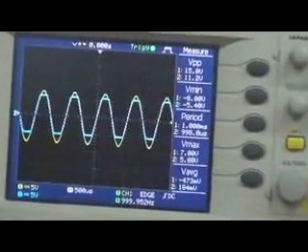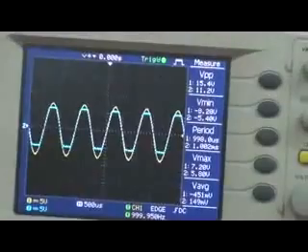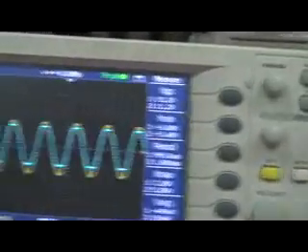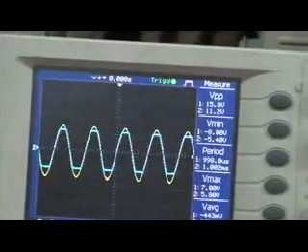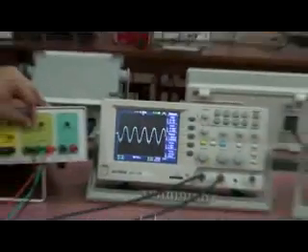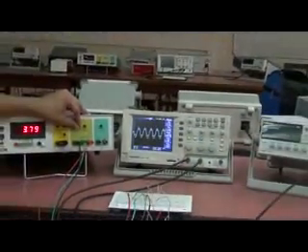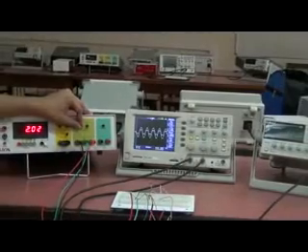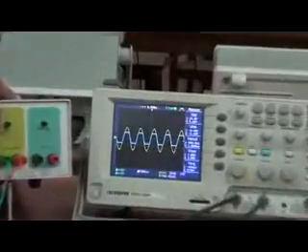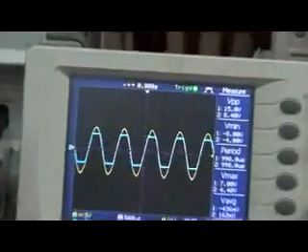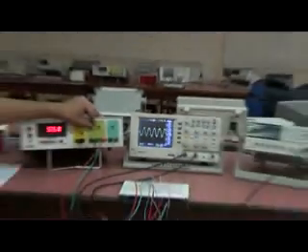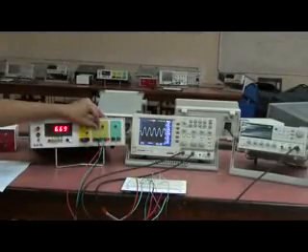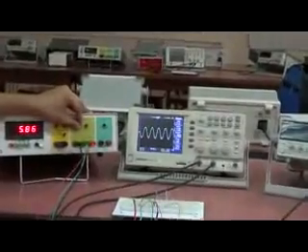So this circuit is called a clipper. We can vary again the clipping through varying the power supply given to the circuit, that is VB and VB dash. We can have different clipping values by just changing the power supply.